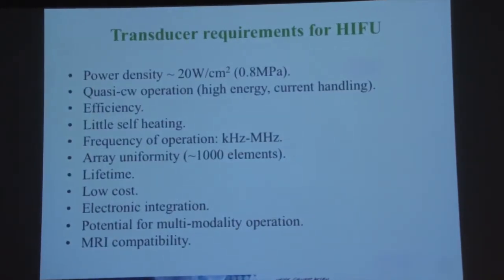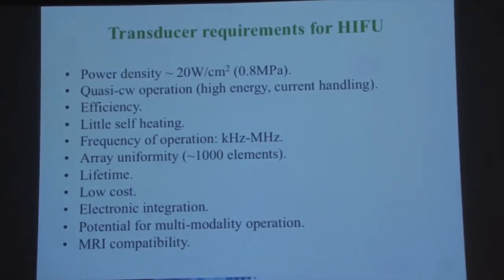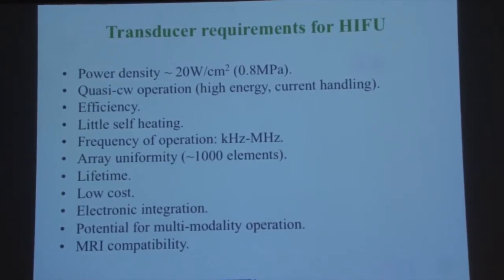So let me also say a few words now about the ability of CMUT to do HIFU. Typically in HIFU application, what you're trying to get is something of the order of 20 watts per square centimeter at the face of the transducer, and then you use focusing gain to deliver much higher powers at focus to do your burning. It's plus or minus this, but this is sort of a nice number in the mid-range. It's a high energy application because, as opposed to medical imaging, where you excite the transducer with a pulse, you're using quasi-CW excitation over a number of cycles, where the treatment could be in times of the order of seconds.